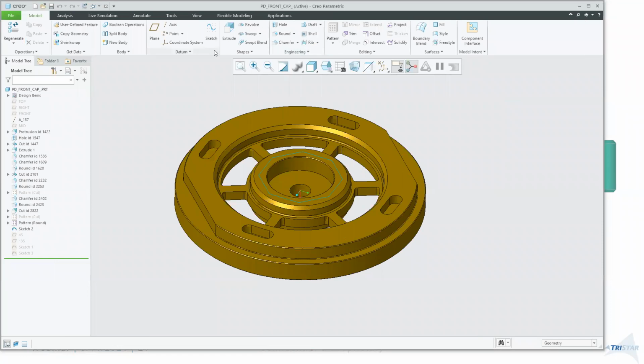Yeah, that's a good point. Maybe combine them, or at least give an option inside of helical sweep to get those standard options. But not there yet. In Creo 8, it's not there. So good questions. One of the common uses for that is analysis. You don't care about showing threads normally, but you want to for analysis, or for a picture. Yep, absolutely, for doing a contact analysis, maybe a bolt analysis. I see what you mean.